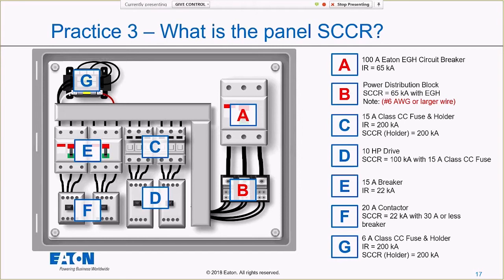Now, if I were going to a large horsepower drive, no problem. But going to those two, you'd want to actually verify that those would accept that wire, and then of course you're going to worry about your wire bending space. Number 6 wire is more expensive than a 10 or a 12, whatever you would actually use for this in the real world. So this is a solution, but it's not really a great one. So what else can we do here?